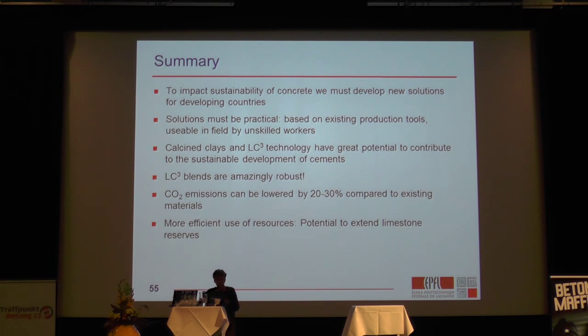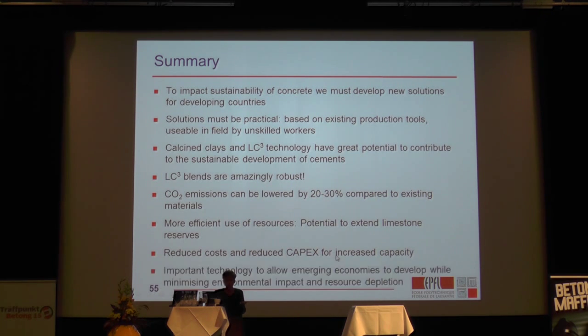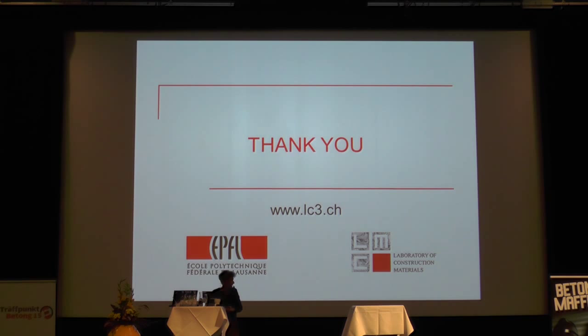And using this technology like calcined clay, you can produce twice as much cement from the same amount of limestone. You have relatively low costs and reduced capex, and therefore I think it's an important technology to allow emerging countries to develop while minimizing environmental impact and resource depletion. And with that, I'd like to thank you for listening and hopefully answer questions if you have any.